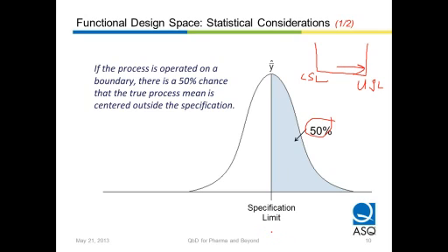So now let's say that the actual process is operating right at the spec limit, and I saw this happening quite often. Well, you would think that 50% would be out. However, whenever they got a high value, they would retest it, and because of the variation in the test itself, they would actually test the product back into specification. When I say test the product back into specification, that's a joke, because of course you can't test something back into specification. But they thought they had done so, so they would pass the product.